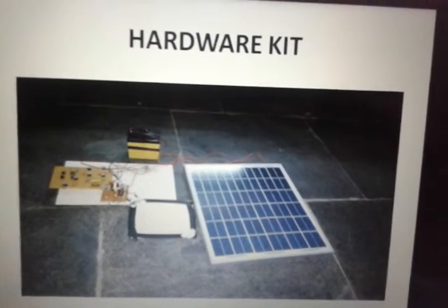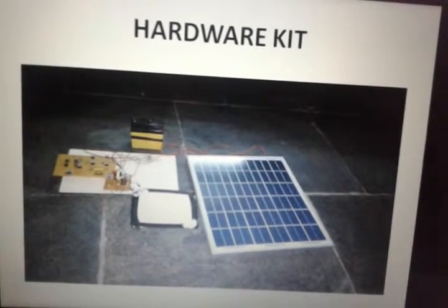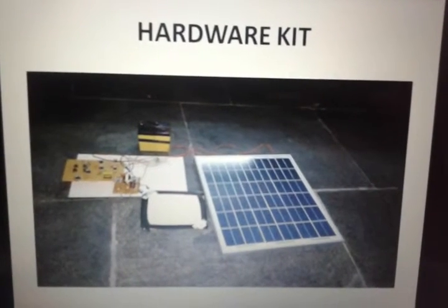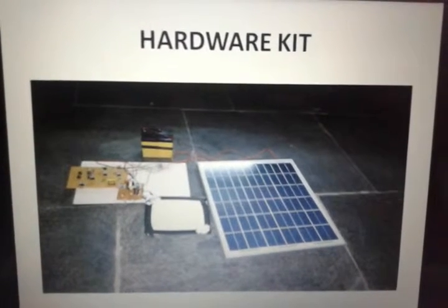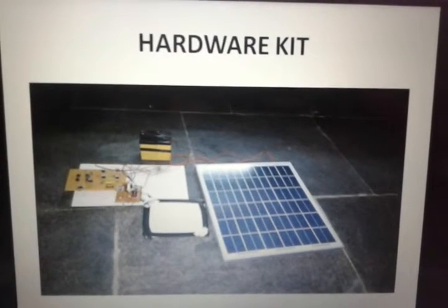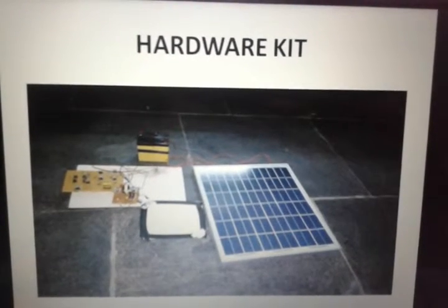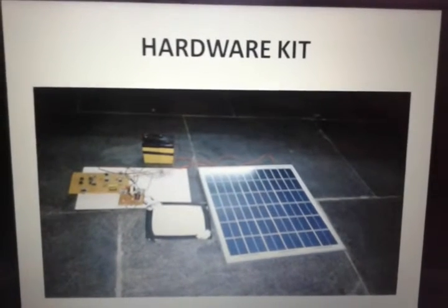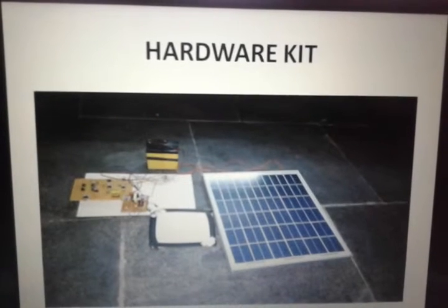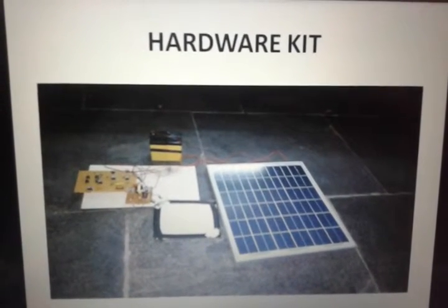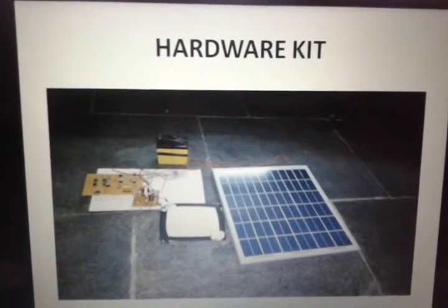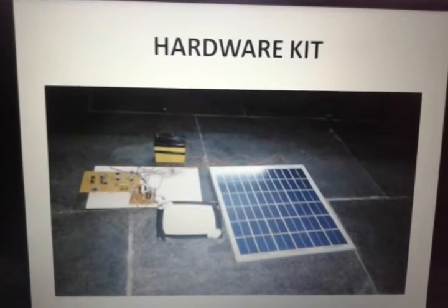Resonance is created across the inductor and capacitor when a system is able to store and easily transfer energy between 2 or more different storage modes. Soft switching can mitigate some of the mechanisms of switching losses and reduces the generation of EMI. During the occurrence of quasi resonance, zero voltage switching takes place and turns on the transistor. ZVS is usually preferred in converters. Thus, ZVS eliminates switching losses induced by diodes and stored energy in the output capacitors. Thus, the DC is converted to AC.